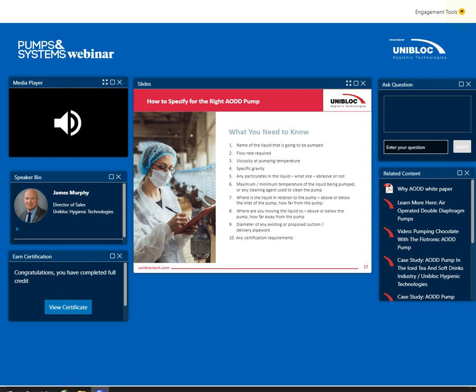And then any type of certification requirements. Is this a scenario where they're pumping a food product and they need something that's 3A certified or FDA compliant? Or, as we mentioned earlier, do they need something that's ATEX certified? So those are the 10 primary questions that we like to put out to our application specialists. And if we can get these answered, typically we can get you moving in the right direction.